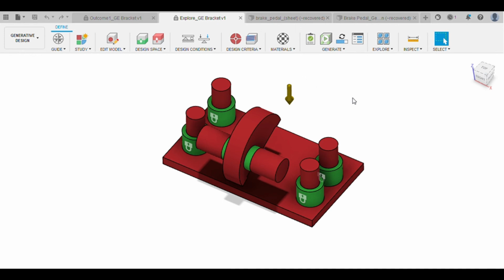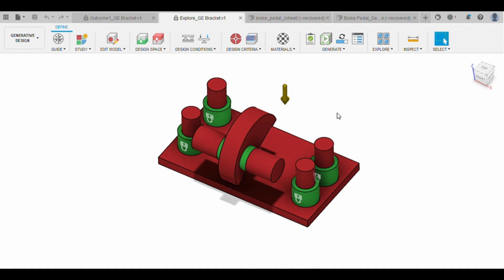And obstacle geometry, that is being indicated red here. So preserve geometry is being indicated green and obstacle geometry in the red. So obstacle geometry is used to represent spaces that one needs to avoid. So on those spaces material flow should not be there. So that is generally used for assembling of components and the material that is being flown. In the generative design process the material would flow in an optimized manner to reduce the weight.